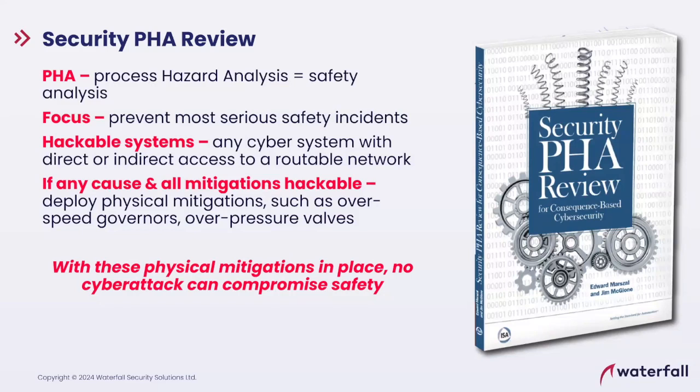The recommendation is, if you can, and if you've got one of these dangerous hackable events, put an unhackable mitigation in, put an electromechanical mitigation in, like the pressure relief valve, like centrifugal overspeed governors, so that even if a cyber attack causes the problem, we avoid disaster.